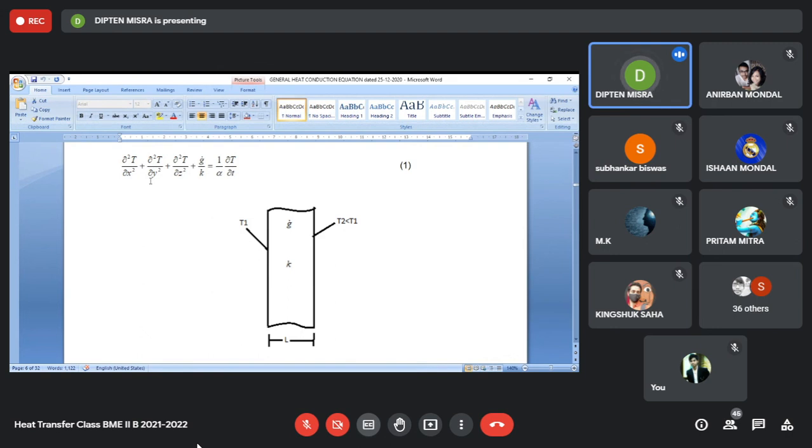And whenever you see this equation, when you become accustomed, you will understand that this is a problem that represents heat conduction only along x. It is a 1D heat conduction. Also, it represents heat conduction which is not changing with time. So it is a steady state, one-dimensional heat conduction problem. So when you see an equation like d2T dx square equal to 0, what does it imply? It implies the mathematical description of 1D steady heat conduction without any internal heat generation.